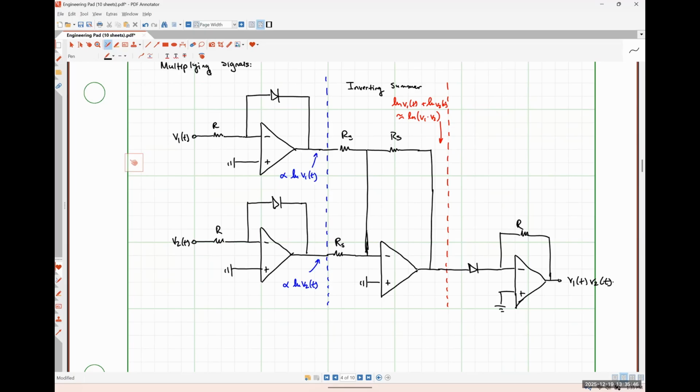You fix that by placing a resistor in parallel with your energy storage element, which forces the initial condition to be 0, but that also slightly changes the relationship of the circuit. So really you need to choose that resistor so that at the frequency of interest, it looks effectively like an open circuit. But that's something we'll cover when we learn Laplace transform to analyze circuits; the math behind that will be way easier than it would be to do right now. So that's why I didn't do it here.